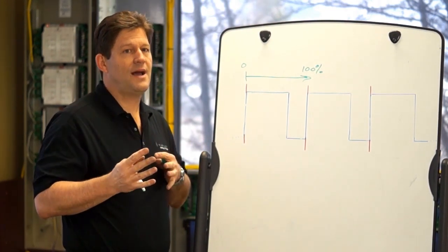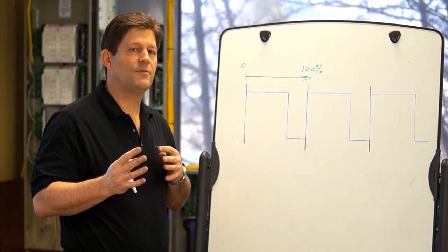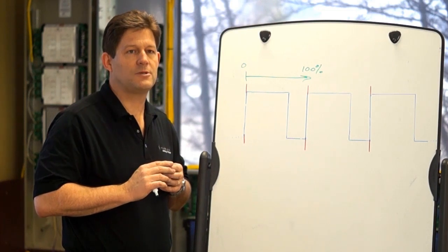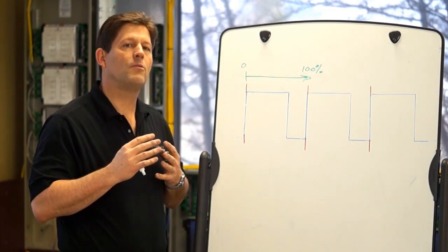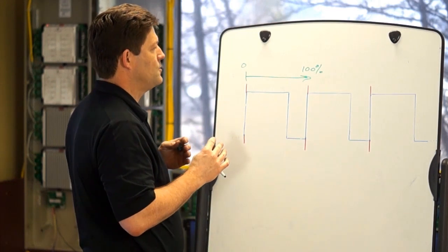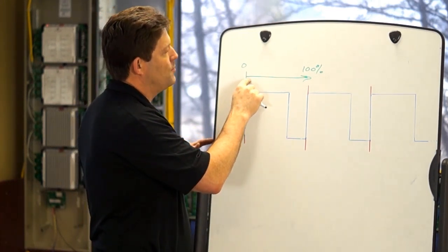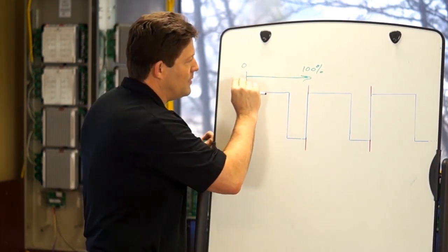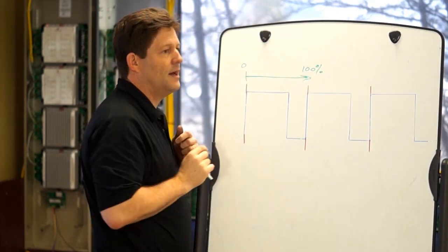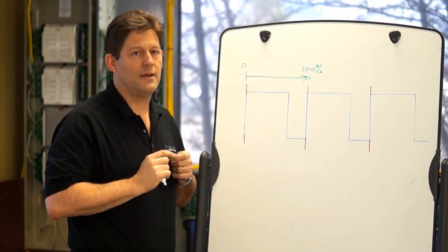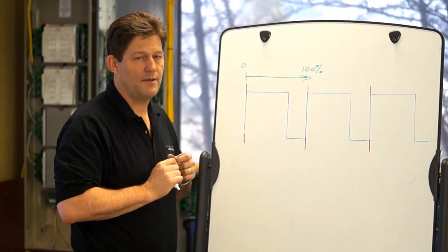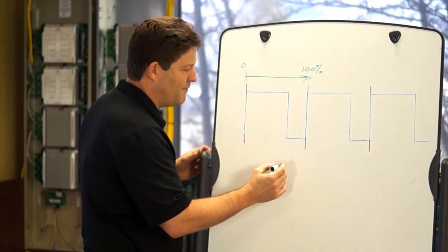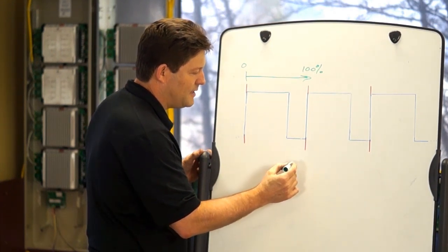Now, because it is opposite of what you'd expect, you do find from time to time manufacturers of PWM controlled light sources that don't comply and go more with what you would expect. With those light sources, if I apply the voltage 0% of the time, then I will get 0 light output, and I will increase linearly up to 100% or full output when I get to applying voltage 100% of the time.